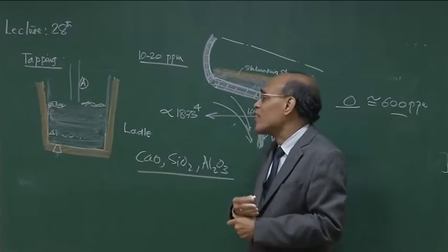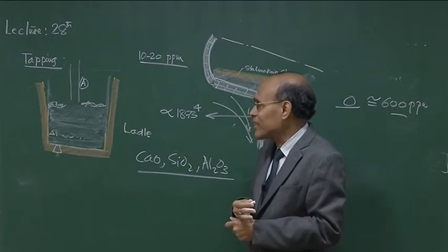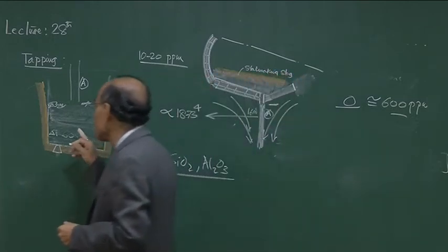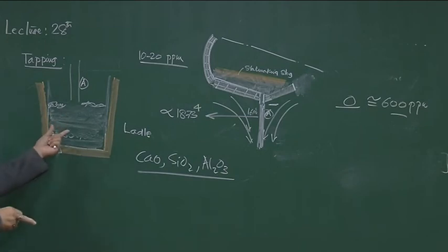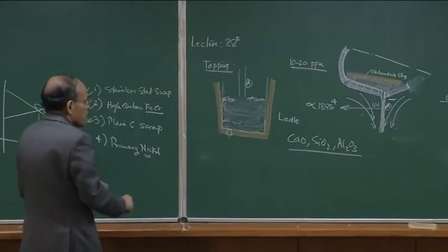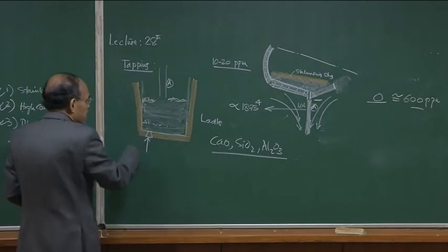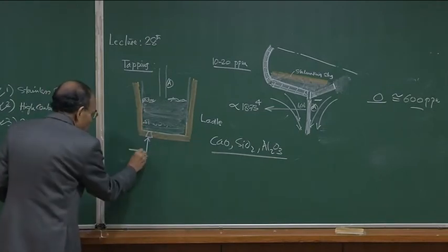It cannot be made autogenous, because we have driven out carbon and silicon from the hot metal itself. It therefore understood that we may have to heat the molten steel with an additional heating source, so as to satisfy the thermal requirements of the downstream processes. So, we will have heat and mass transfer taking place in the subsequent stages. So, there is going to be a provision.